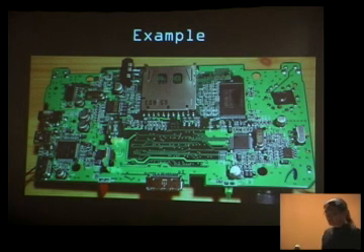It's a GP2X, which is a little video game system. And so you can look at this, you apply some of your motifs here and sort of what's going on. So here's a Samsung part. I know Samsung makes flash ROM. It's got to be flash, right? I see over here WM, that's Wolfson. Okay, that's a codec, so that's audio.